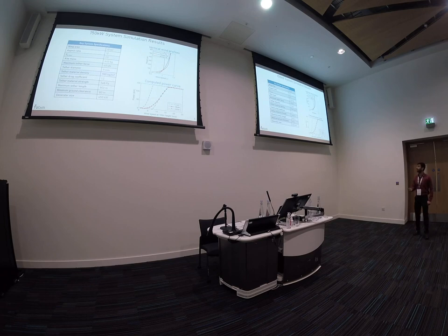I guess the key parameters here are the wing area, aspect ratio, and CL max, but these can be obtained maybe in a different way for soft wings. For example, the mass and the tether we can model the same way. But the difference there is more in the transition phase and the reeling phase, because for this particular fixed wing system, I assume the kite can easily glide back to its starting point. But soft wings have a slower transition phase and then a reeling phase, so that needs to be done for a soft wing system. For fixed wing systems, it's easy to evaluate.